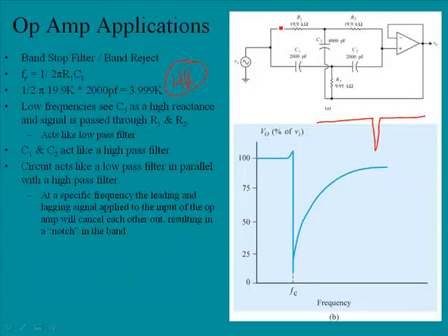And so here we have a signal coming in here, and a signal coming in here, and the signal coming through here will come through, but it will also go through this RC. This is actually an RC network, which will cause the signal to lag a little bit behind, and then the signal passing through here will lead that signal. They'll both reach this, and there will be a point where the two will tend to cancel each other out, and we will end up with a notch.